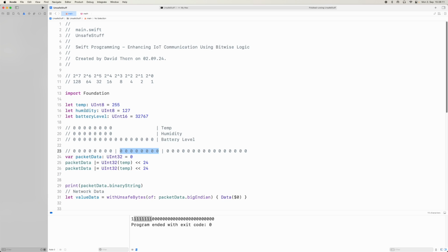With that said, we can now come to the next sensor that we're going to place the data in, the second portion, and that's humidity. Using the same knowledge here, we know that we can have 16 zeros to the right hand side of it for it to sit in the right position. With that said, we're going to left shift it 16 zeros to the left, or we're going to take 16 zeros and place it to the far right hand side of these 8 bits.